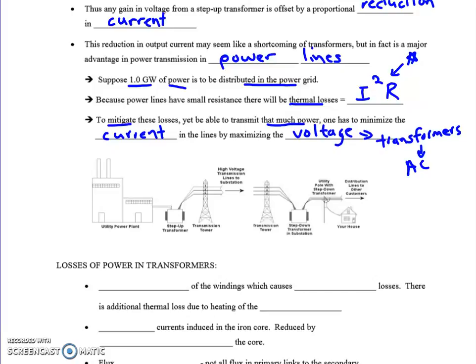So let's say we have a power plant. Well, that dynamo in there is probably generating voltage at around 220 volts, based on the angular velocity and the magnet and all that. We're not going to be producing hundreds of thousands of volts directly. So what comes out, we step up for the power lines to, let's say, 500,000 volts, or 500 kilovolts. That might be traveling for miles and miles at very, very low current.